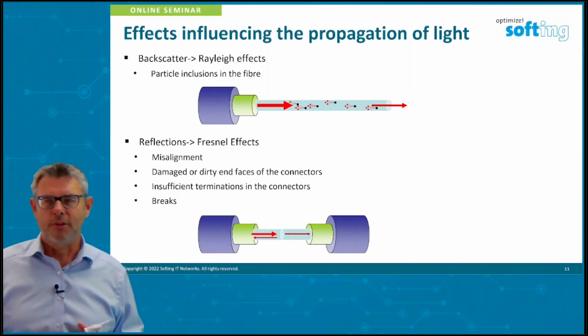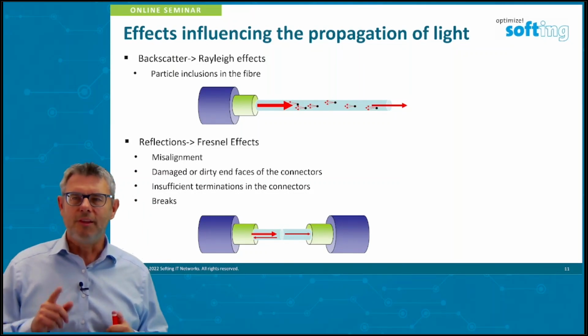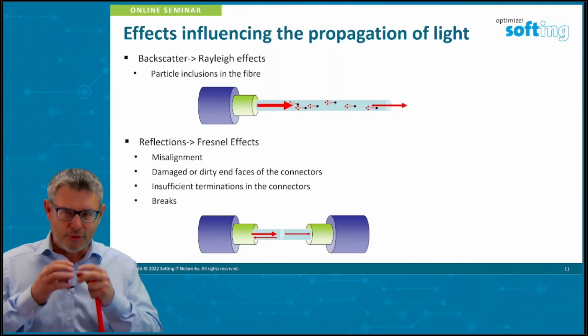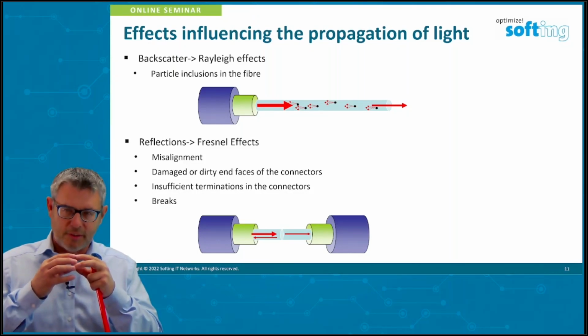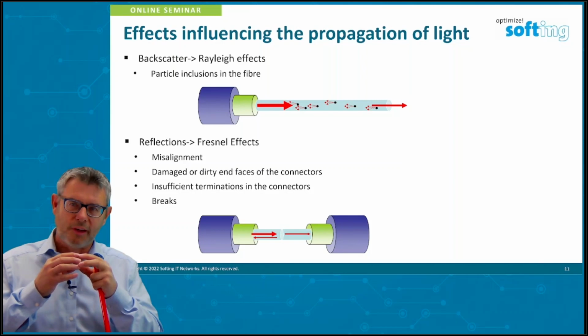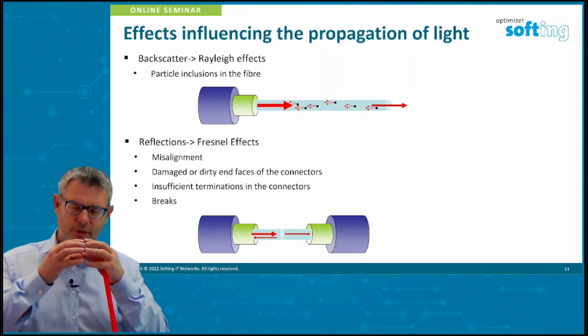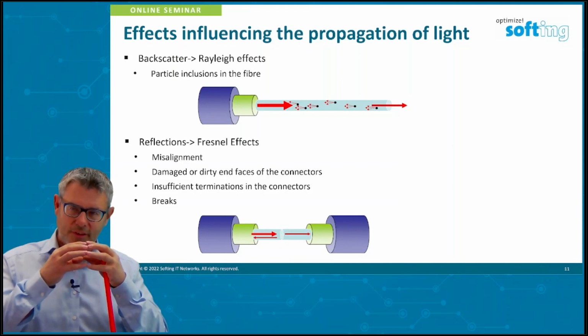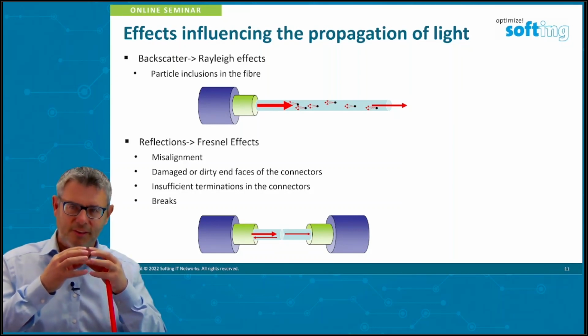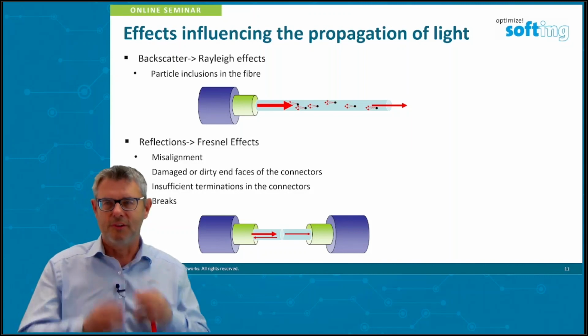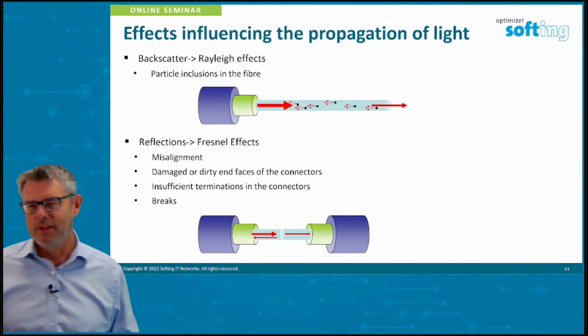And if you see on single mode, we have a core diameter of 9 micrometers, and we only have a sleeve with a little tolerance, about 1 micrometer. We already lose 10% of our, let's say, area where we meet at the connector points. So mechanical precision is very important in fiber optic connectors.